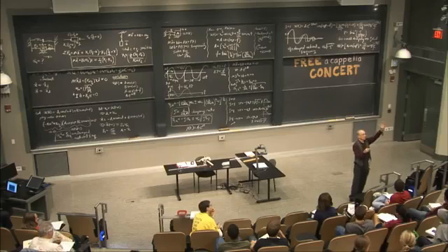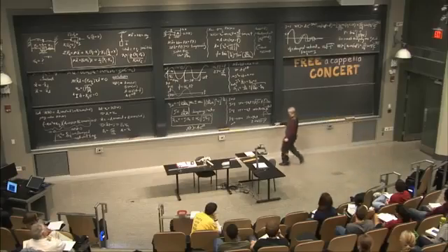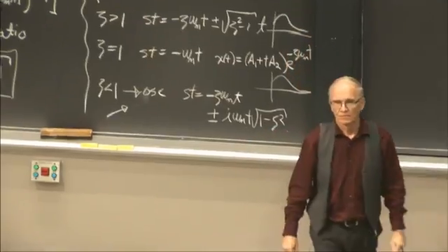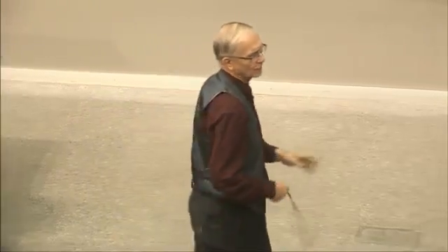And the answer you always get from people is damping. Why? Because everybody's been taught this thing, and they all assume that the change in the frequency is caused by damping, but damping couldn't possibly be the reason. Because with 20% damping, this thing will die out in about 2 swings and it's done. That's a lot of damping, actually. But it only accounts for a 2% change in natural frequency, not 15. So what causes the change in the frequency?